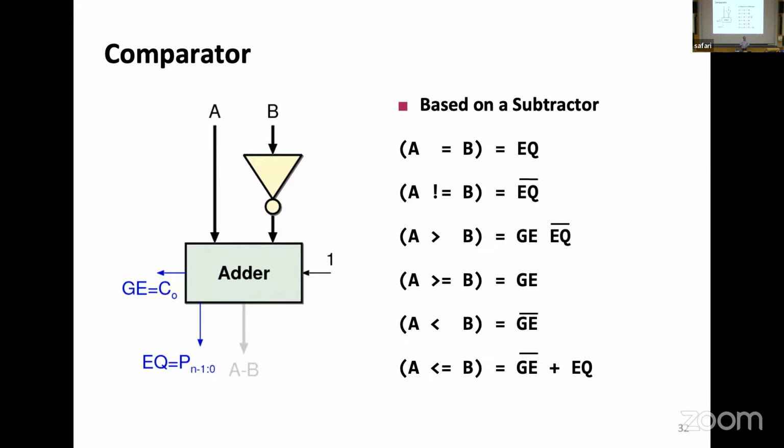There are some internal signals in some ways, which I might explain in another lecture. When I make the A minus B, I can figure out if they are equal, not equal, larger or equal, smaller or equal, very easily. That's a comparison, and that comparison will become essential when we are making our processors, because frequently you write programs, loops that have a clause that terminate. You say, if A something, do this, else do something else. What happens in the processor, he subtracts them, looks at the result, and based on that, he can make a decision.